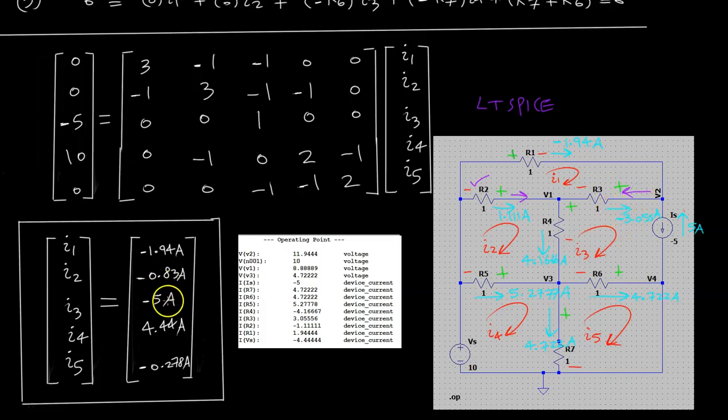The MATLAB calculation says that the current through R3 goes to the right, and it's a negative sign though, and so LTSPICE tells us the correct direction in this way. But I3 is the mesh version, so we have to keep that in mind. We can't just mix up the branch and the mesh currents.